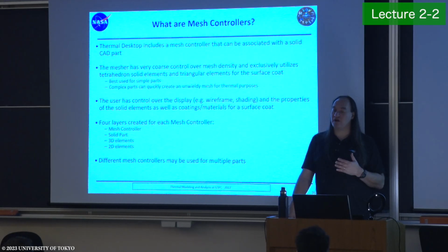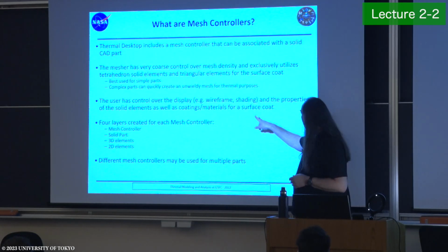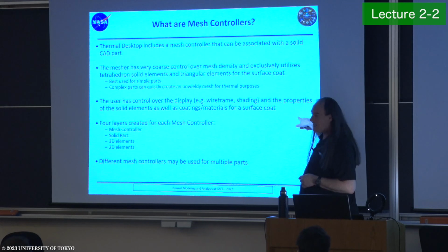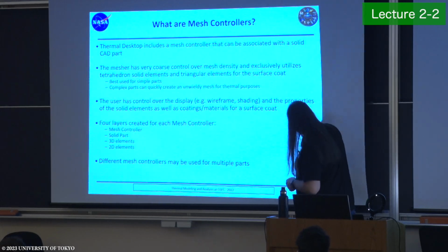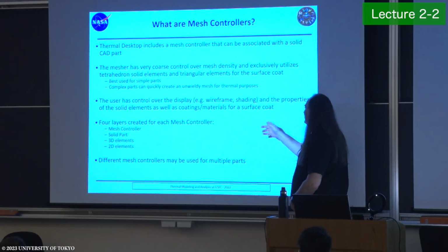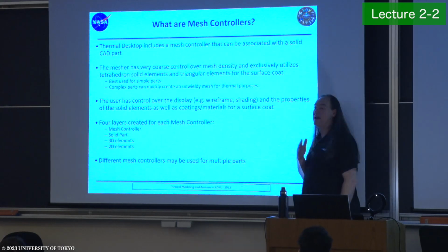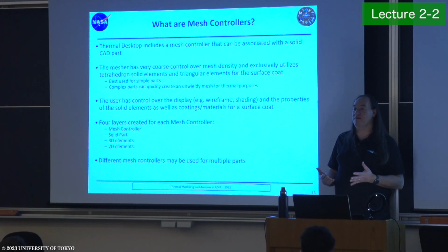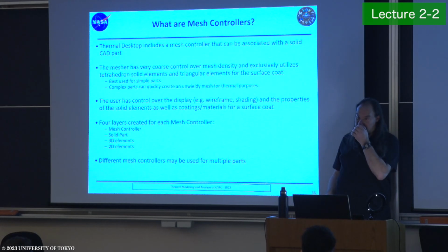Myself, I much prefer a quad to a triangular, mainly because if I've got a quad, I get the cross diagonals. If I've got 2 tris, I get this, and I'm missing this diagonal that's in there. So if I've got a bunch of those, I'm not really getting the heat flow in that direction. So when I can, I always prefer to do quads as opposed to 2 tris. Tris, however, are great because they're always planar. 3 points define a plane. I could have a quad that has a little bit of a skew to it, as we've seen here. So there is that negative to it.